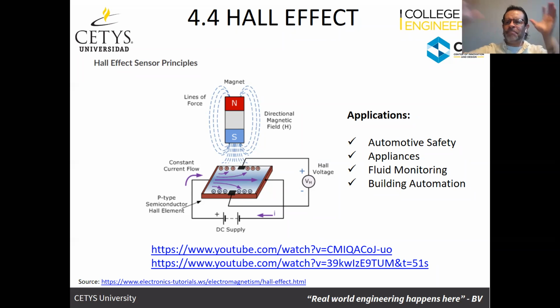Do you agree with that? The impact can come from any place in the car. So, okay, I'm going to put a bunch of sensors all over the car, so if it's being hit by something, the deployment occurs. Well, actually, the deployment should occur whenever the seatbelt has a very sudden reaction that reflects an impact. That's when the deployment of the airbag should occur. So the Hall effect sensor detects that.